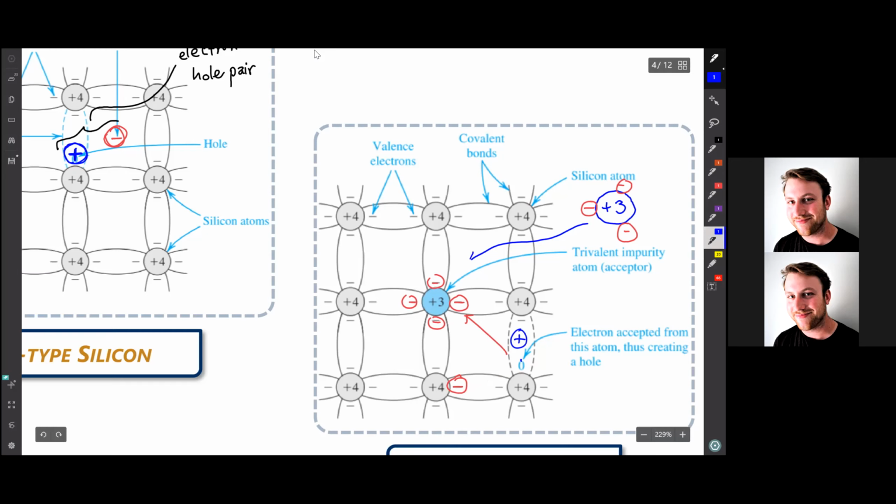So in this case of a p-type semiconductor, if that free charge is depleted from this region, we will have a +3 kind of charge from our donor, sorry, excuse me, our acceptor, but we don't have that hole around any longer to balance out the +3. So we actually have less positive charge.